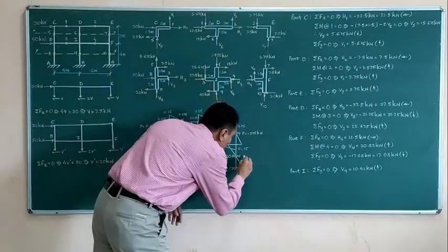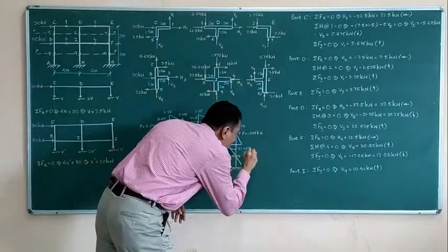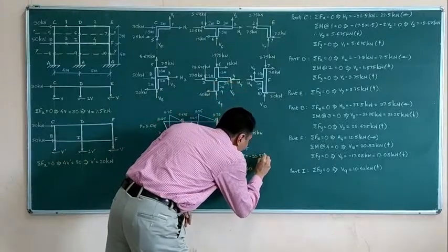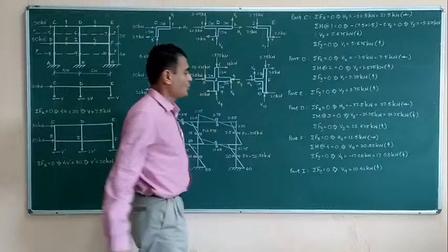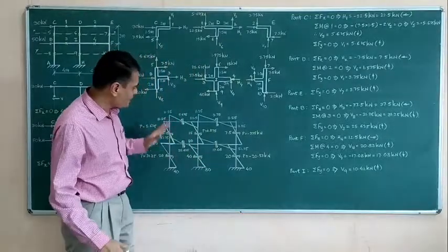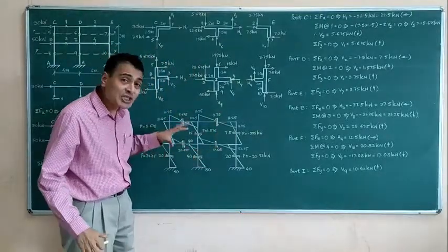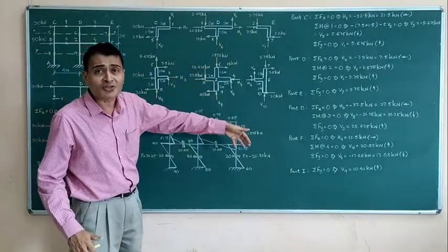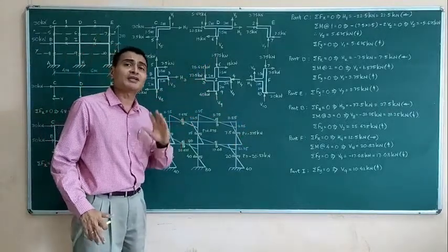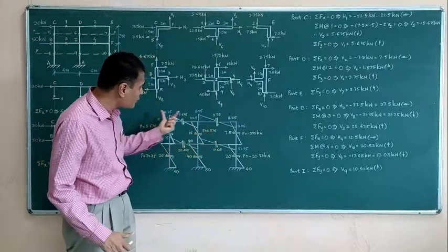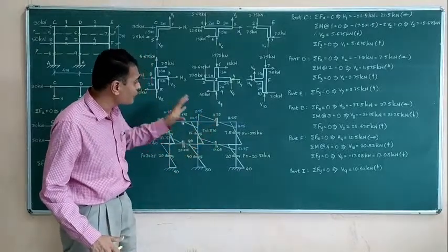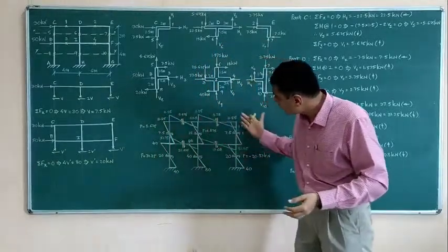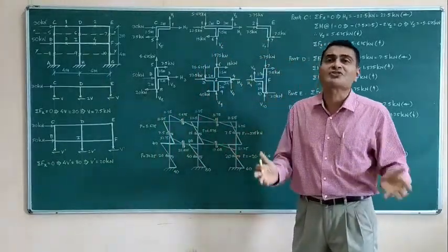So again here you are able to write P equal to negative 20.83. So likewise, please write all axial forces, depending upon pushing means negative, compressive, and pulling means positive, that is tensile. Just mention the values near each beam and column. Otherwise, as far as shear force and bending moment are concerned, you have actually written the values at the appropriate places.